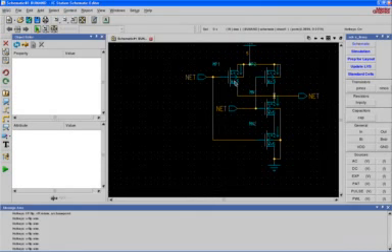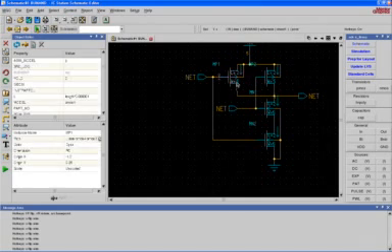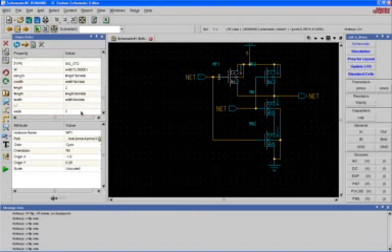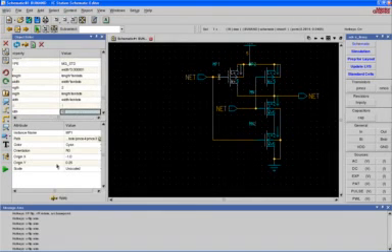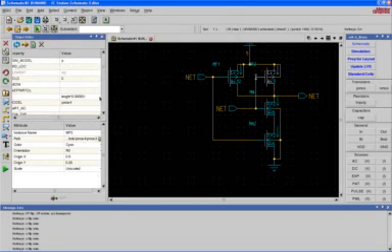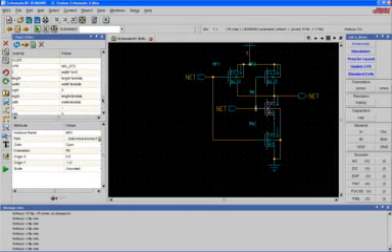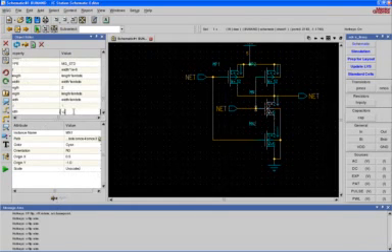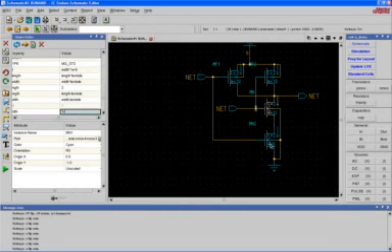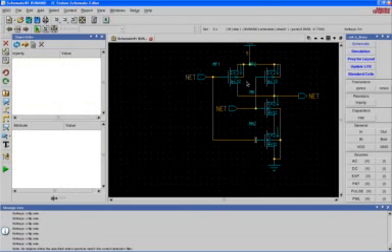And if you look at my handout, the size for the PMOS both need to be 12. The width needs to be 12. Okay. The width needs to be 12 on this PMOS as well. Both NMOSs also tend to have a width of 12 for the NAND gate. And why this is the case, we'll talk about in class. So let's set all the width of all 4 transistors to 12.